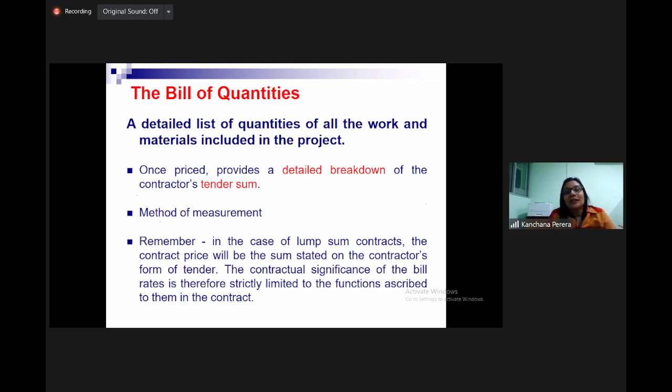As you mentioned, they must do 12 ACs for the given amount if it is a lump sum project. If it is a remeasurement, we can negotiate with the consultant. Why? They have priced it only for one air conditioner in the document. Some consultants argue it should go as a variation. That is the fair way of handling. But in lump sum, it is not like that. Why? The lump sum figure is given for the total construction of the work, covering all the specifications and drawings.